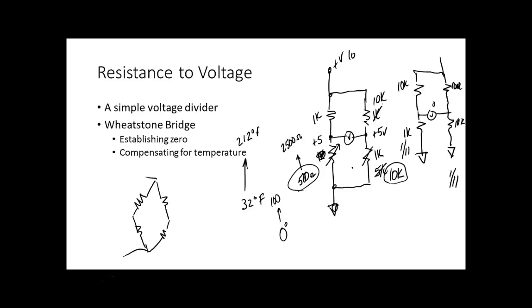And what's nice about it is here we got centigrade. The problem is that what happens when this goes below is this right here. Well, what happens now is this will become positive. I'm sorry. Is that the polarity of the voltmeter will change. So if your voltmeter shows a negative voltage, it means it's below your reference. If it's a positive voltage, it means it's above your reference.